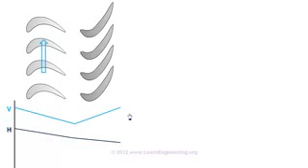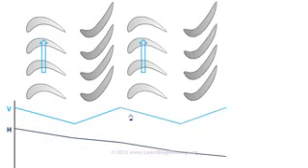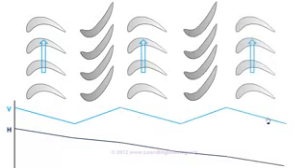Now we have increased the velocity of the fluid, so we can put the next set of rotors. Again stator. And again rotor. So in a steam turbine there will be alternating sets of such rotors and stators. Rotors, which are moving, are attached to the hub. Stators, which are stationary, are attached to the casing of the turbine.